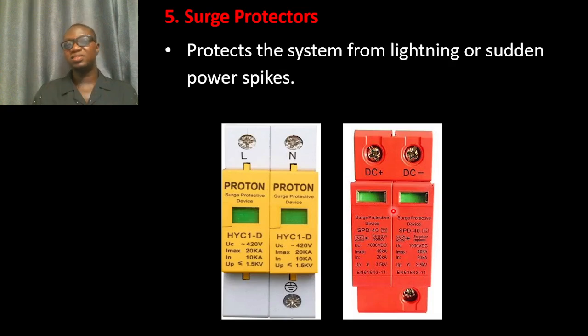The other thing we look at is the surge protector. This one protects from lightning and sudden power spikes. You can see it has an earth terminal to help redirect whatever surge to the earth.